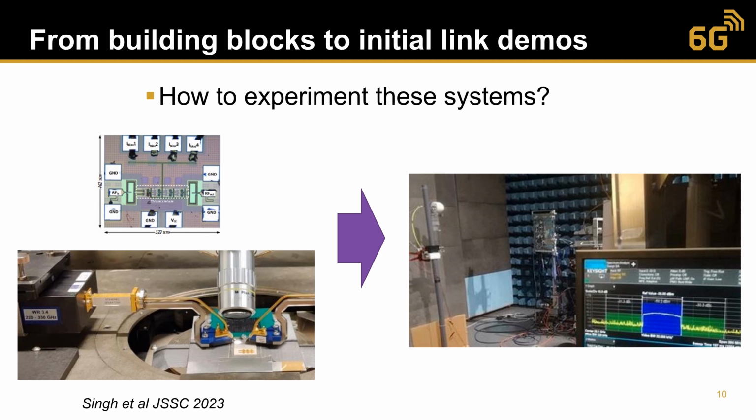When all RF IP blocks are integrated in a complete RF transceiver, then the OTA measurements will take over. The conductive measurements will be needed for the debugging phase of the IP blocks, while OTA testing is system-level testing where debugging the operation of individual blocks within the transceiver is no longer an easy task.